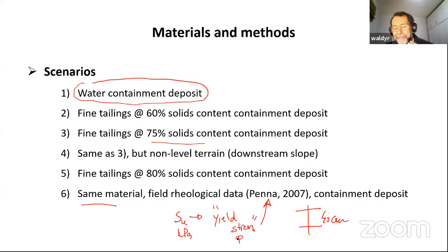Here you have a Pa scale. When you try to make a torque on that vane and rotate it, it's going to shear the material, and then you're going to measure what they call yield stress. But in the scale of Pa, the continuation of this scale is what the geotechnical engineers call undrained shear strength. Okay.